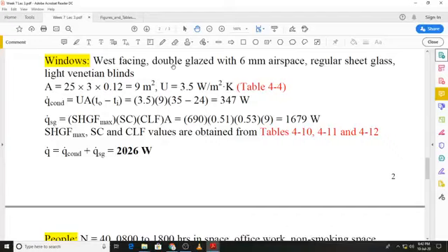TI is the indoor design temperature, which is given to us as 24 degrees C, and the temperature TAV is the average outside dry bulb temperature, which is given to us as 29.5 degrees C. So we just insert those values and find out the value of CLTD adjusted, and then find out the heat gain through the roof, and that is what's done in the solution. So we go back to the solution and find out what's the resultant heat gain.